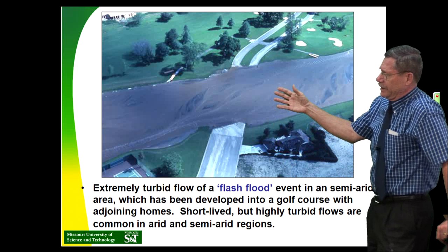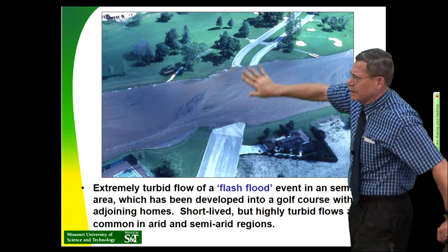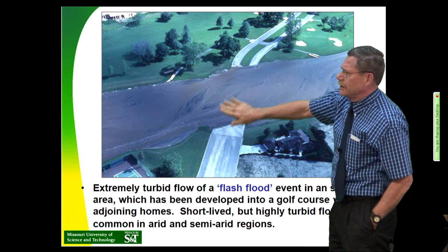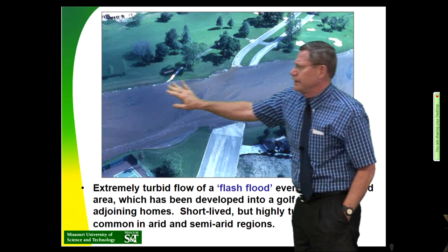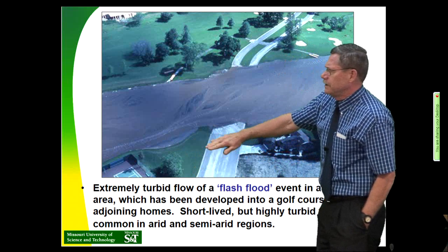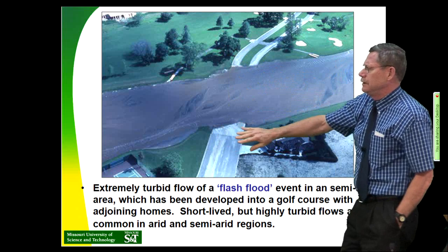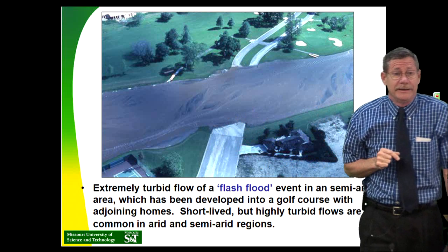This is the same thing they deal with in Arizona. That's why they call it an Arizona dip. These type of flows are infrequent enough that you just come in here and clean it all out later, and you just accept the aggradation in the channel, and you have to live with it and work with it, because the cost of diking this thing and putting clear span bridges is colossal compared to how often you might use them. You might only use them once every 10 years, something like that.